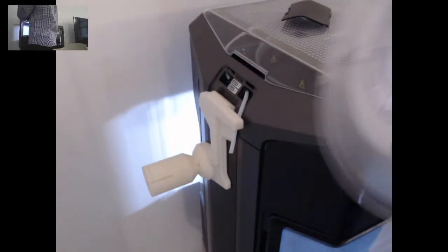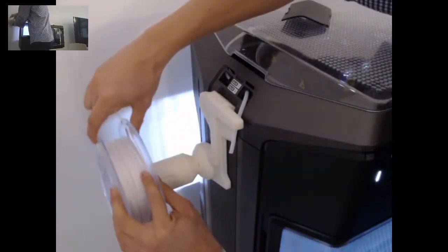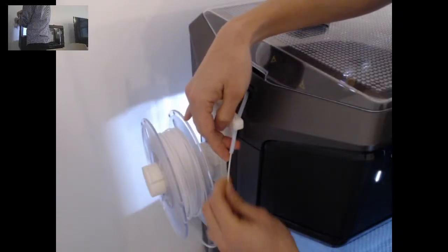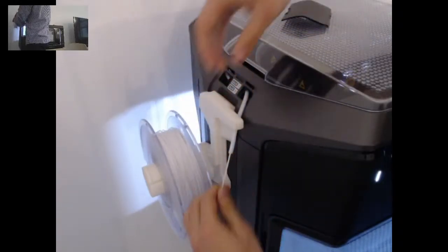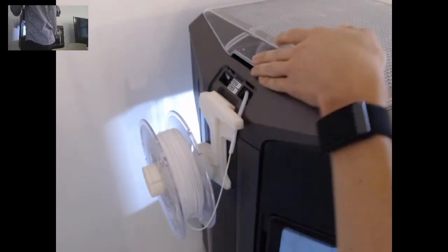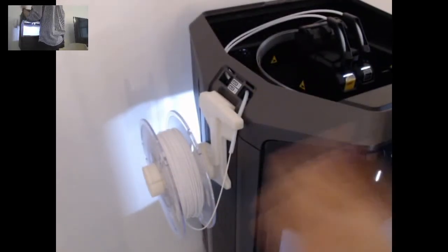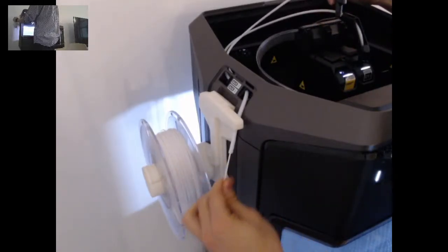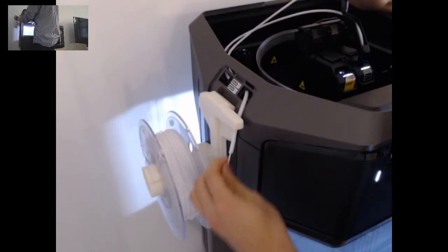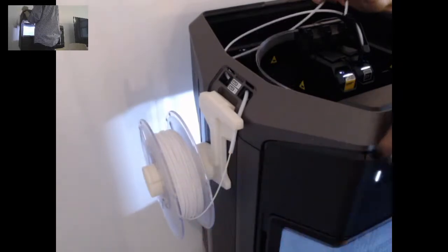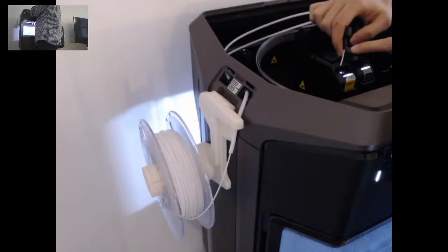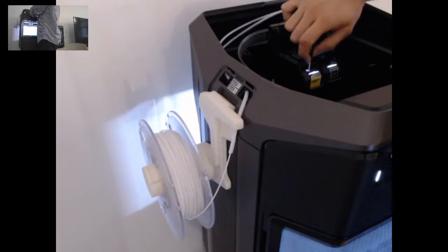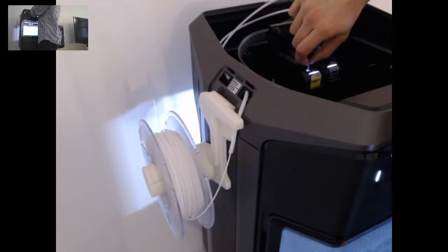And now I'm ready to actually place my material in there, just as I would with any other external caddy, and route the first tip of my filament all the way through. I'll open this up again, but all the way into my last extruder. Since you're routing it manually, make sure the filament is going through like so, exposing a little extra tip of the material, and then guide it directly into the extruder itself.